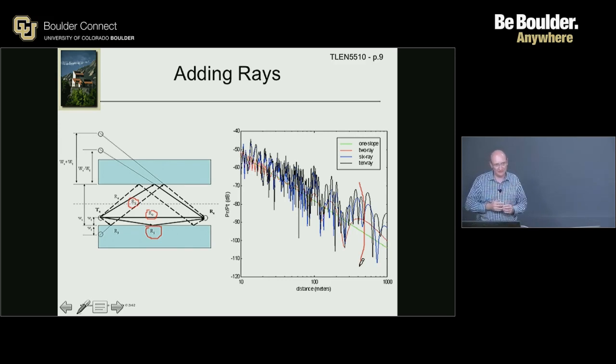If you sum them up, you'll get a final graph. If you sum all the ray power levels, that's what this does, yes. This is not each individual ray; this is the sum of all the rays. If you don't sum them up, they all look like the green line, a little off because the distances are a little different, but not much. But it's by summing them that you get that in phase, out of phase, that you get those deep fades.